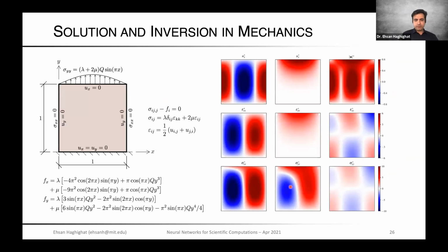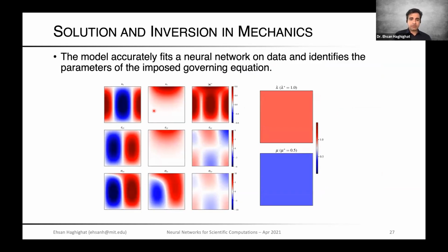The first one we looked at, just experimenting, was this elasticity problem, subjected to these boundary conditions and also these complex body forces, just to get a pattern, essentially. We solved this as a forward solver, so no data, like the Burgers' equation I showed you, subjected to boundary conditions. We also solved it as an inversion problem. Assuming that you have a displacement field, from digital image correlation or some other approach, can we set up a neural network to find the parameters? And the answer is yes, with the physics-informed architecture, and we find the parameters that accurately represent this.